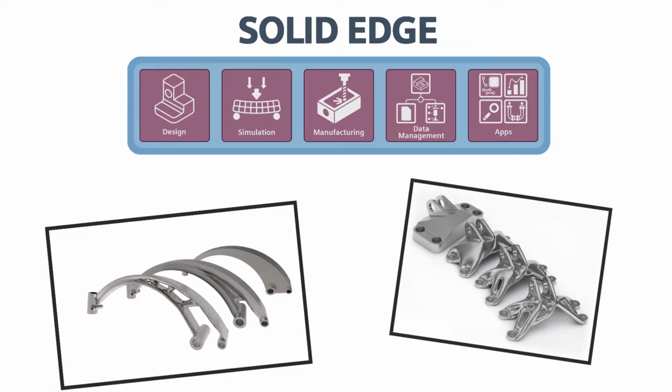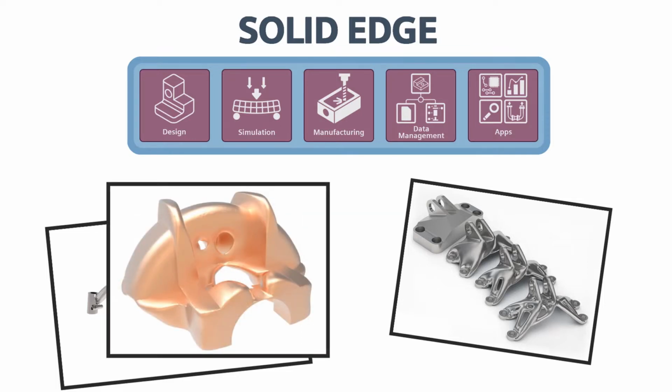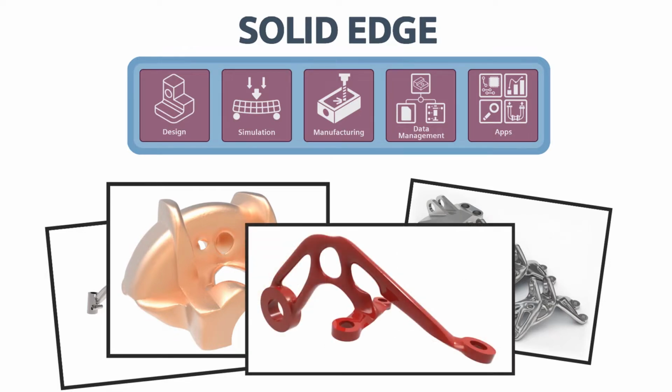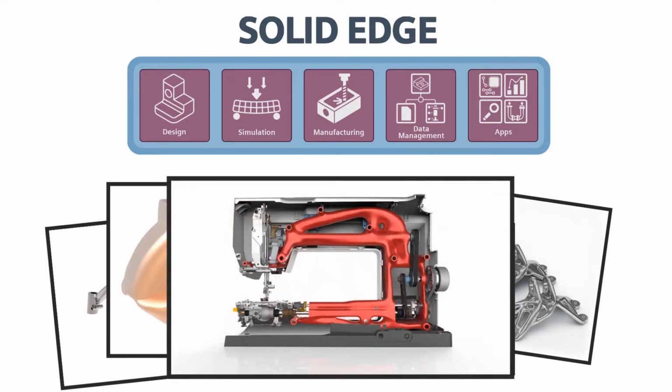Our tour today will be looking at some of the next generation design tools, which include generative design, convergent modelling techniques, and additive manufacturing. Generative design is a process whereby the computer will create an optimised design for us based on the use criteria of the part. This allows us to ensure our components are as lightweight as possible while minimising material usage and saving costs, all whilst maintaining the structural integrity required.